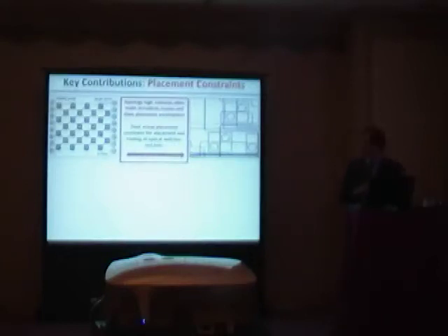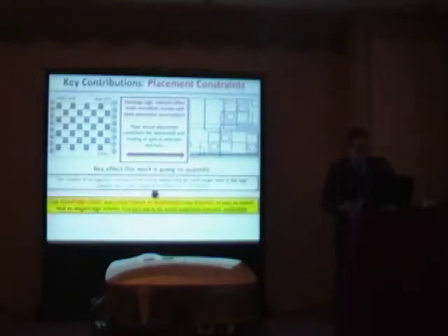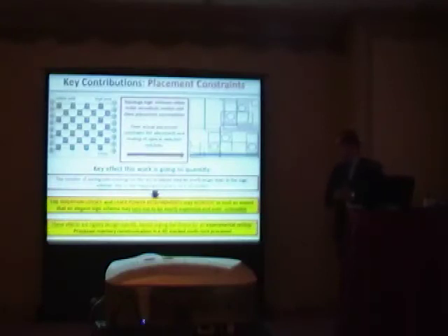In fact, when you place and route an appealing logic topology into its physical implementation under the effect of placement and routing constraints, especially in those cases where the logic topology is characterized by unrealistic placement assumptions, the situation becomes unrecognizable. The first key effect is an increase of waveguide crossings in the real layout. As a consequence, the insertion loss and the laser power requirements may worsen so much that this appealing logic topology becomes overly expensive and in many cases unfeasible. So these effects are strictly design specific, and then I urge the choice for an experimental setting.